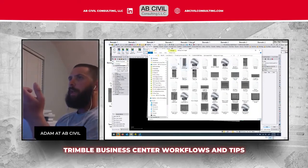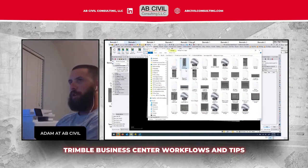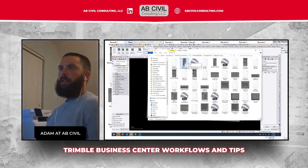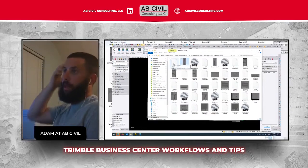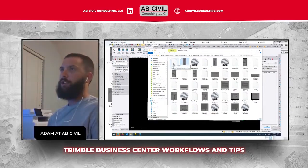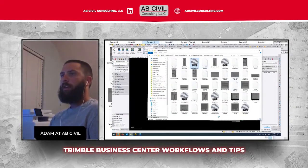So every time you write an image to this folder, it writes 3 files. It writes your image file, which you see here. It's able to be previewed in Windows. It writes a GFW, which I believe is the file format that Trimble uses to read the georeference location of that image. So without that piece, it will not work. It also writes a KML, Google Earth. That is actually not required. You can delete those. But they are actually handy because I'll go to this now.